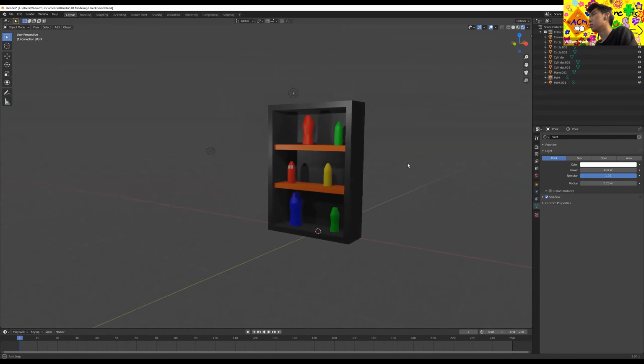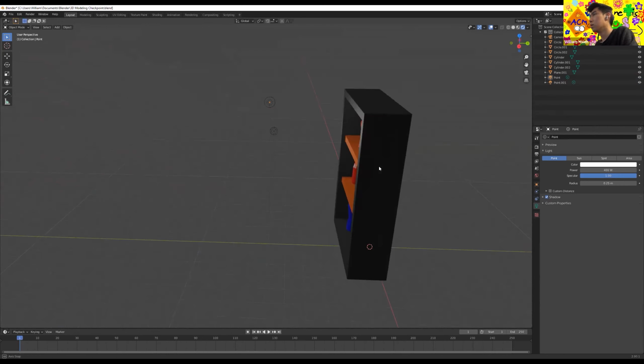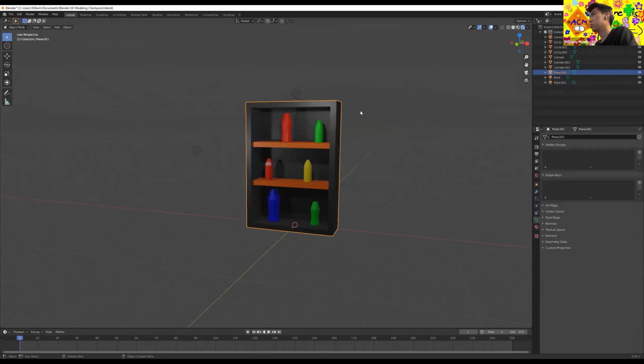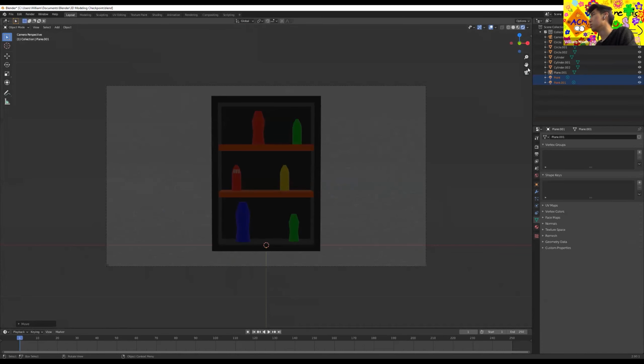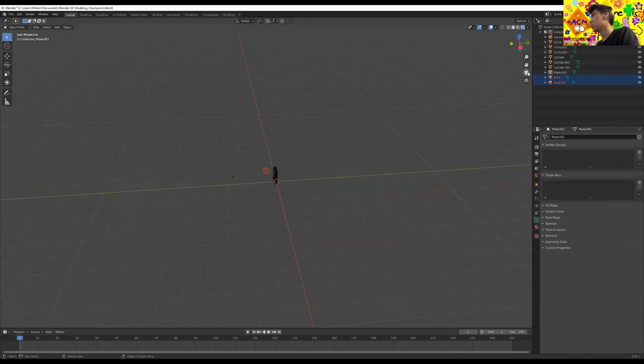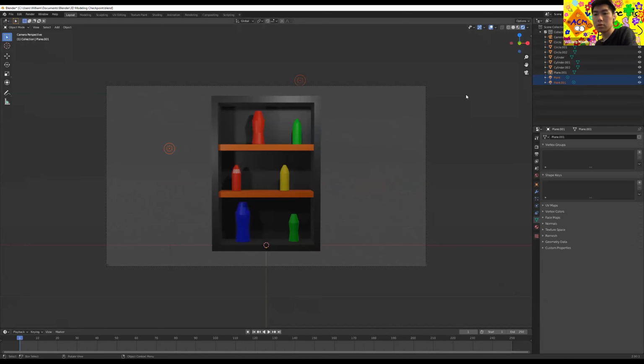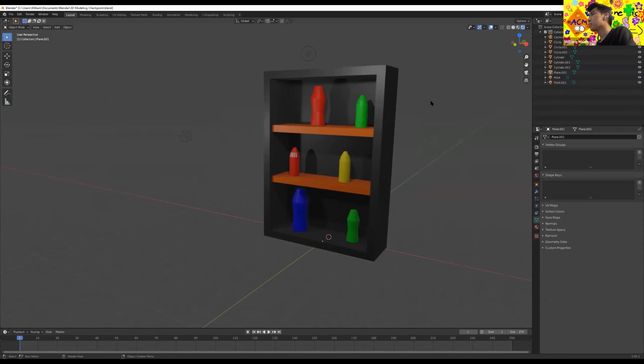The light might be too far away from your scene. You want to move the lights closer to your object, because if it's 200 miles away, you're not going to see anything. All right. Bingo. That's too bright, but working. So you could just tune it from there or move the light a little bit further. It's up to you.